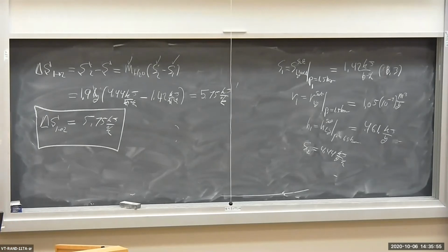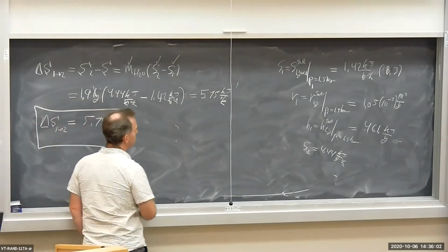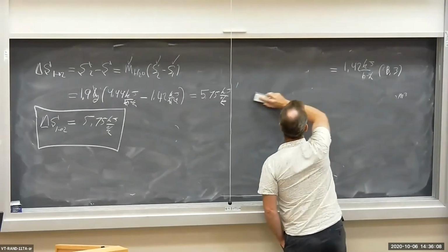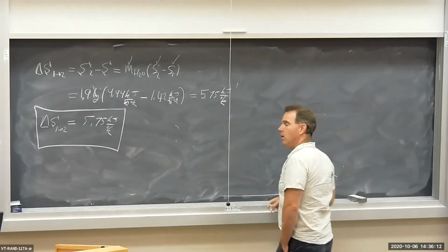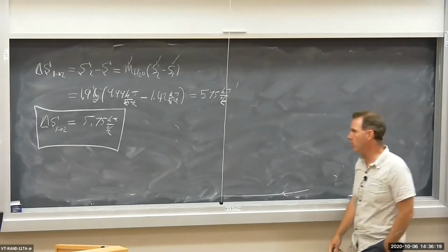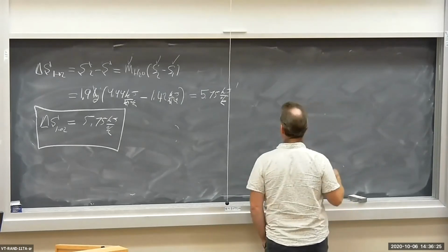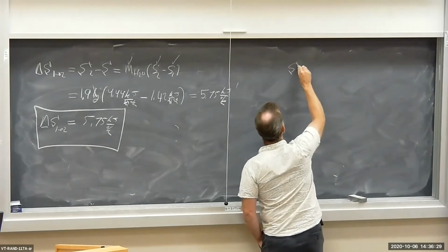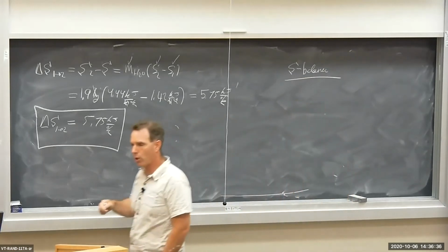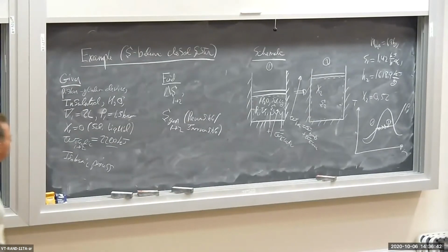All right, so let's calculate S-gen, the entropy generated from state 1 to state 2. What's S-gen? Let's apply the entropy balance to our closed system H2O. Why? Because S-gen appears in the entropy balance. Maybe we can solve for S-gen by the entropy balance. Of course, the H2O is a closed system, so we're going to write the entropy balance.